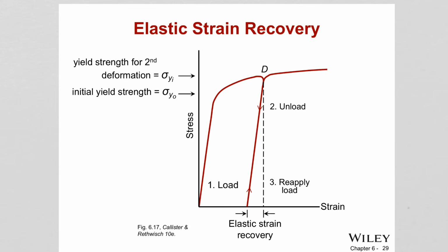As we talked about, elastic strain in the deformed part is recoverable, and that graph is demonstrating that. So you deform the material up until point D, collect stress strain data, okay, and once that happens you remove the stresses, and the elastic region recovers, going back to recovering the elastic strain.